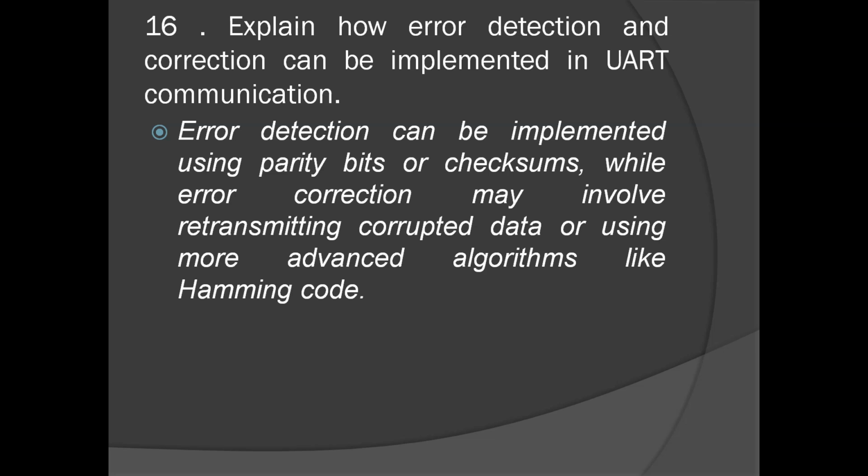So in real time, you will be given that UART module, and if it is not working, how can you decide whether it is a fault of the microcontroller or a fault of the UART module in your hand? How will you check? Through the hardware communication protocol we used. Universal asynchronous receiver transmitter we used to communicate. Yeah, correct.